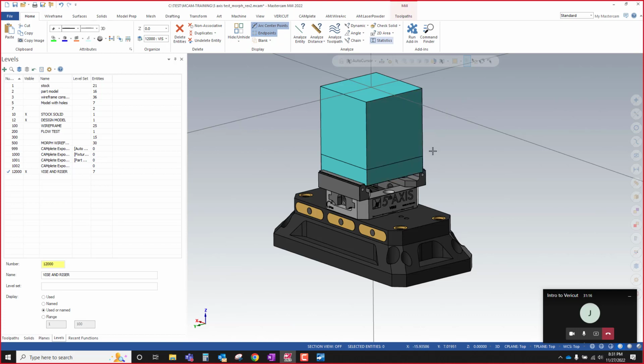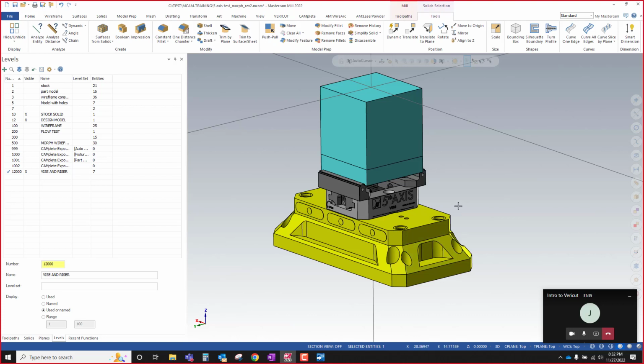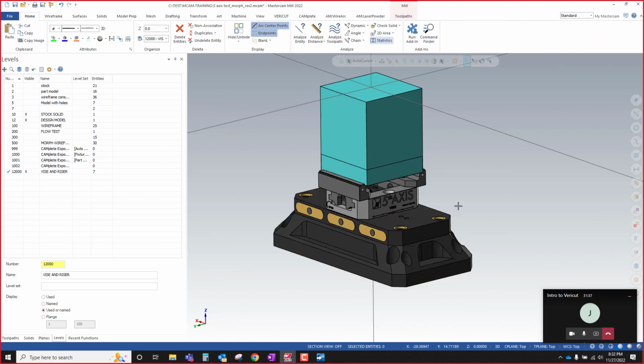We're going to be checking all of the spindle of the machine, so not just the cutting tool, but the holder and the actual spindle nose and the sheet metal. We're going to be checking that for collisions against the vise jaws, the vise, the base, and the rest of the machine itself. So like the B-axis platter on a UMC 750, all that stuff gets checked.